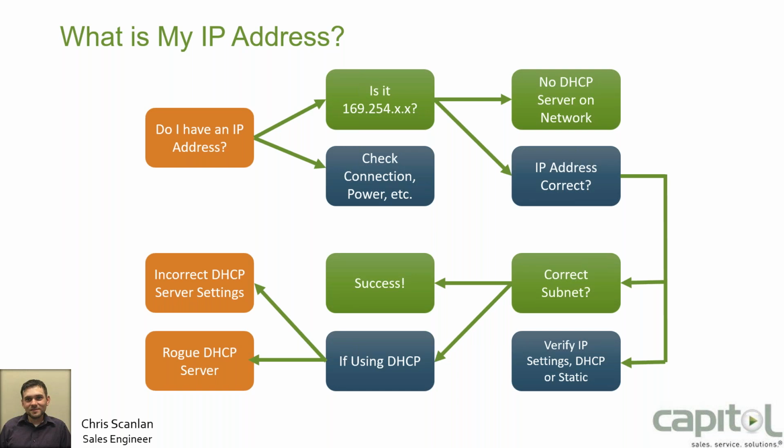One issue I've seen actually happen a lot, retrofit projects. There are many different ways to broadcast signal. There's copper, there's fiber, there is coax, there's MoCA. And MoCA can be a great way for a retrofit, but I've also seen it cause issues, wreak havoc on systems. When you use MoCA, it's broadcasting your signal over your coax, right, instead of copper.